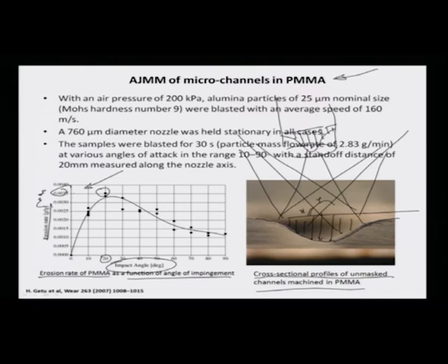This gives a basis which really talks about standoff distances of the nozzle as measured from this plane surface. So probably around this 20 degrees range, the standoff distance is the optimum best. If you may recall, there was a relationship that we derived before in terms of the nozzle tip distance, and we said that the machining rate increases, then plateaus off and falls down as far as the variation of MRR is concerned with the NTD.